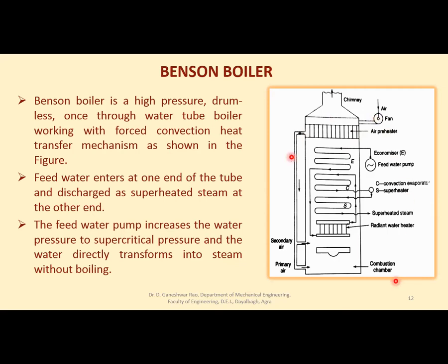Everything is self-explanatory. I'll try to explain. Feed water enters at one end of the tube and is discharged as superheated steam at the other end. The feed water pump increases the water pressure to supercritical pressure, and the water directly transforms into steam without boiling.